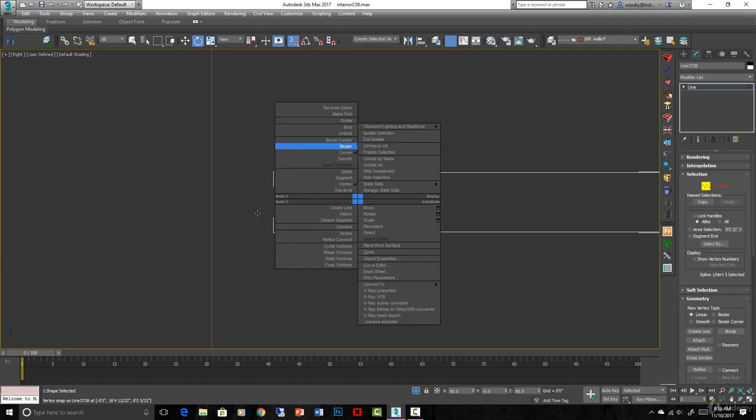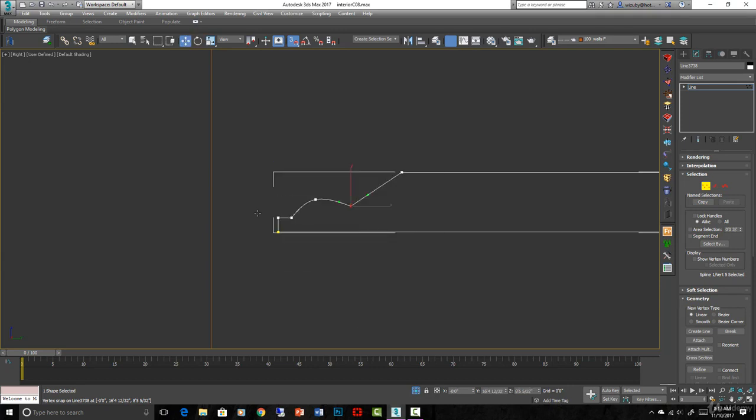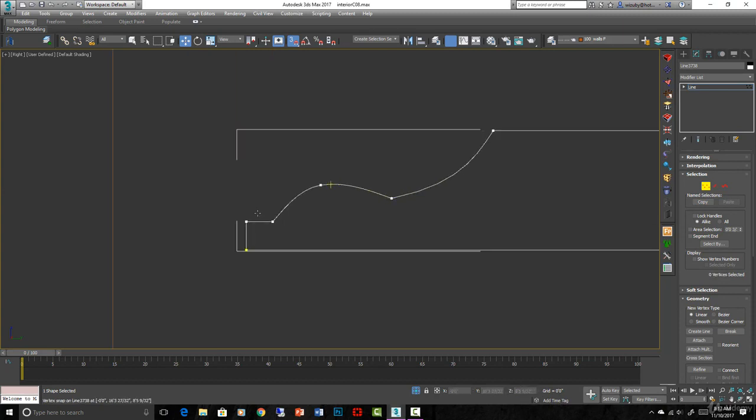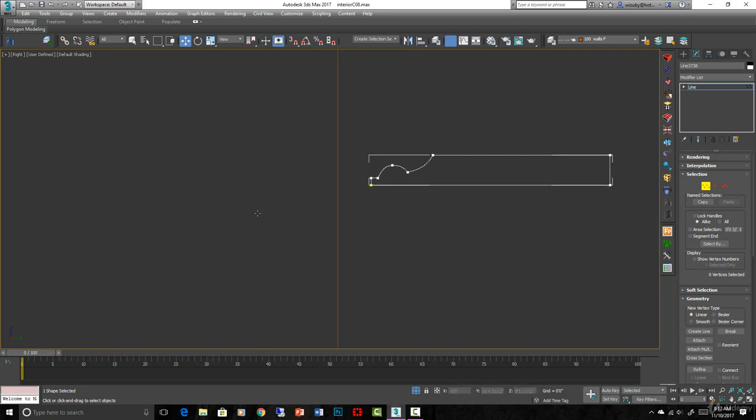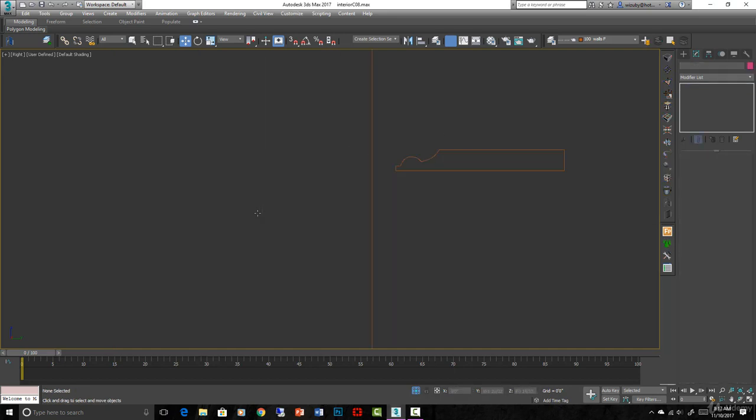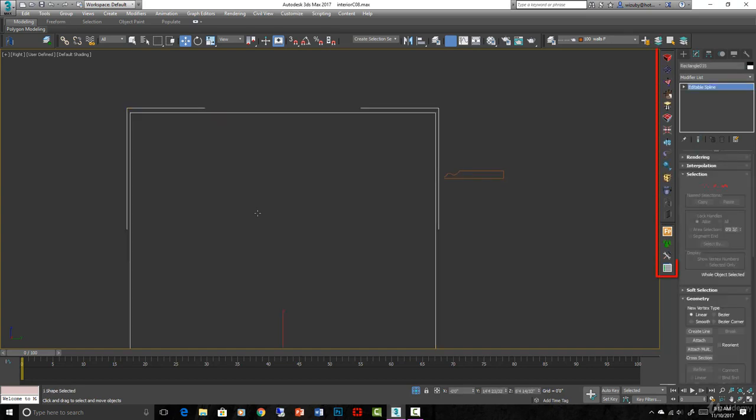Let's take this and make it a Bezier corner and kind of just do that, give it that little edge. And let's take this up here, okay, something like that. All right, so a very basic profile, and then we just took this and we swept